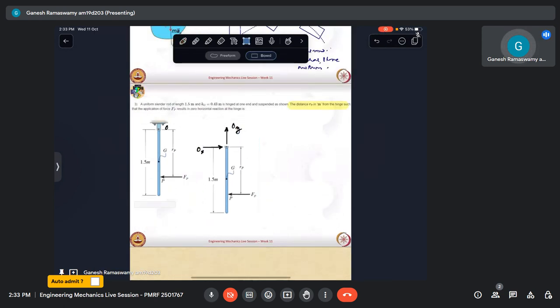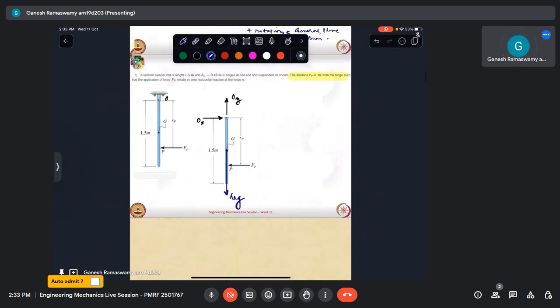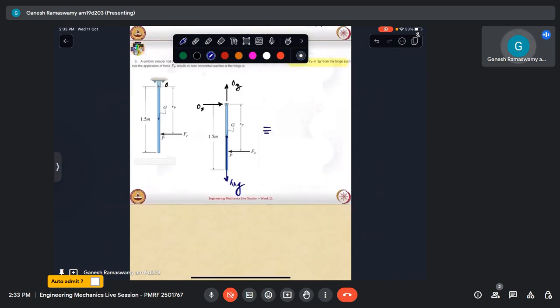So we have drawn the free body diagram, with one point missing where the mass has to be drawn. So we have mg pointing downward, and we have the force. Now if I were to draw the kinetic diagram for this, I know that it will be undergoing fixed axis rotation about the point O. So let us say that it has some rotation, Ig alpha, and then its mass center will have an acceleration.